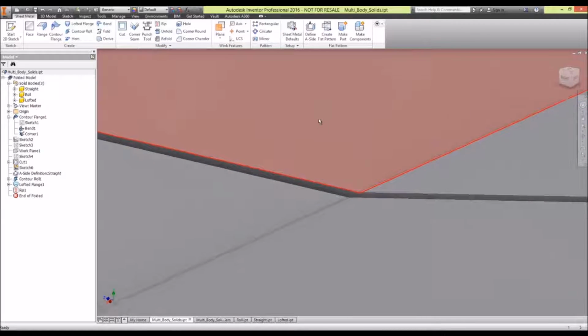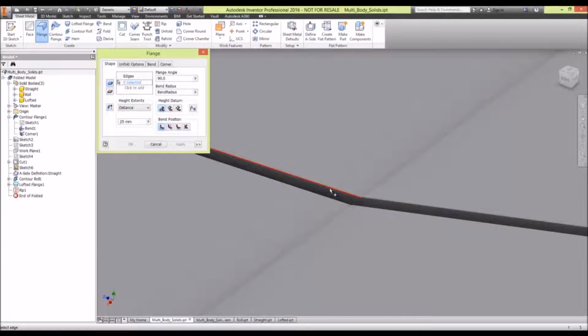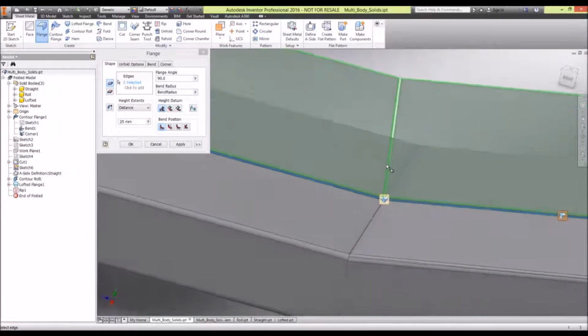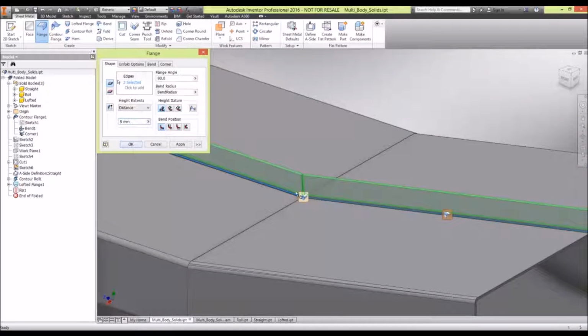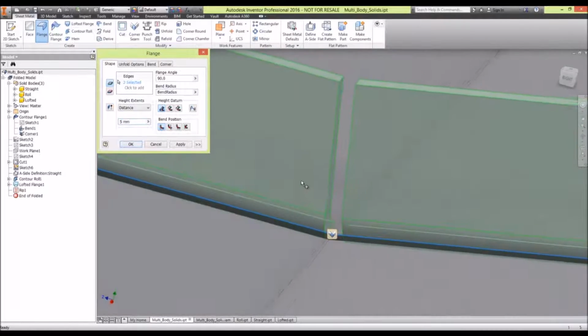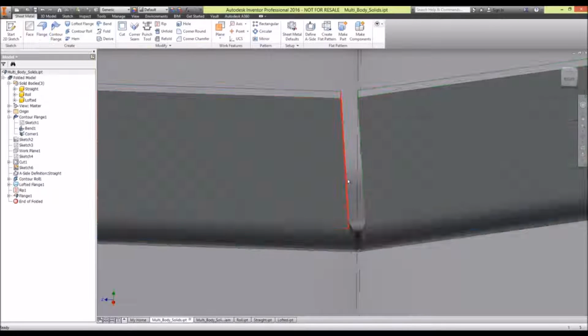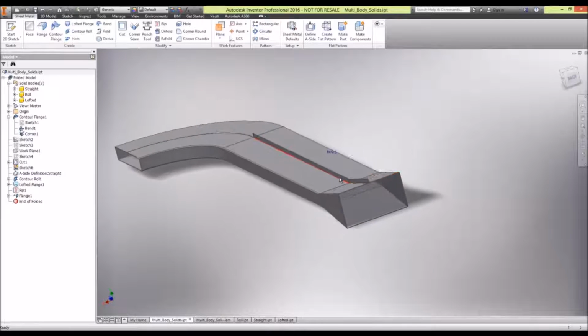So now if I start having a look in here and start creating a flange on maybe that edge and that edge, I've now got two flanges on this particular model that actually interact with one another. Maybe the distance of these is 5mm because they're being bolted together, and they are working. These are two separate solids, but those two separate solids I can actually have as those components.